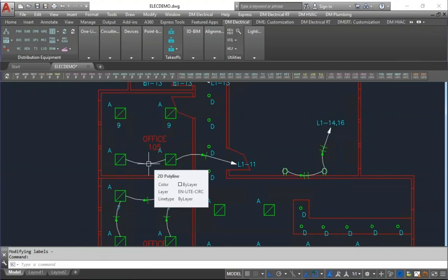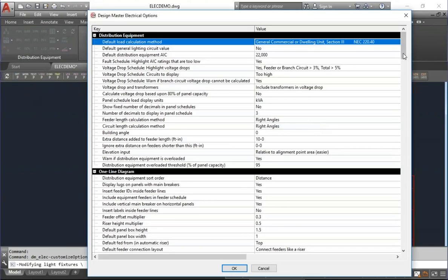It keeps the drawing a little bit cleaner, so it's not as much cluttered. It's also kind of a throwback to when you were drawing the loops manually. It's kind of tedious to keep track of all those loops, so the standard that a lot of people had when they're drafting by hand is to not show tick marks because it's a pain to keep track of. With our software, we add them automatically, so it's not any extra work to show them. It does make the drawing slightly more cluttered, so there is that consideration. But you can be confident that the software is getting them in there and keeping them up to date without any work on your part, so you can show them if you'd like to have that additional information.